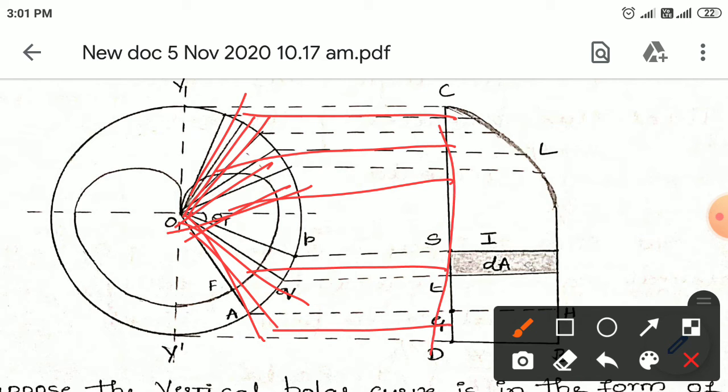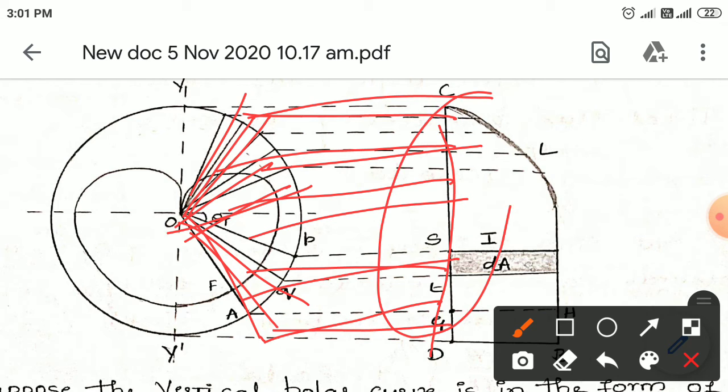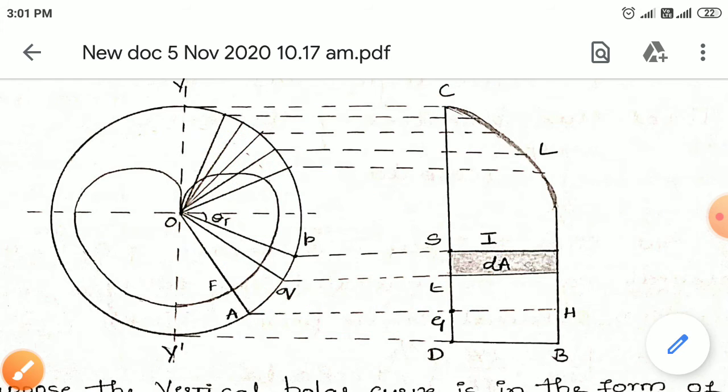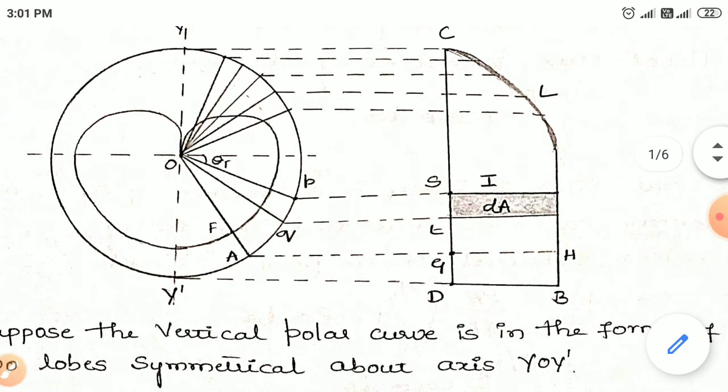By measuring the intensity on that particular parallel plane, you can find out the mean. By taking the mean of the candle powers of all the lamp radiations, you can find out the MSCP, that is mean spherical candle power.